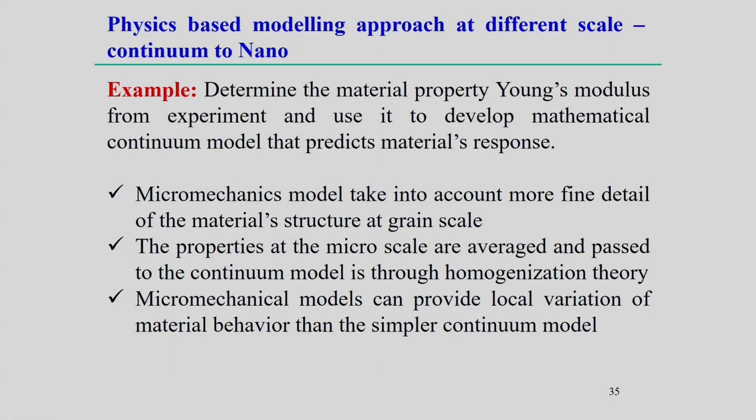For example, determining the material property Young's modulus. We know the Young's modulus we can easily measure in a particular material through experiments, just by using the universal tensile testing machine. That value of Young's modulus can be used in a mathematical model in the continuum model. If we want to develop an elastic stress analysis for a particular material, then there is a requirement of the Young's modulus for this particular material. So, using this value from the experimental measurement as the input property to the model, the model can predict the output in terms of the material response.